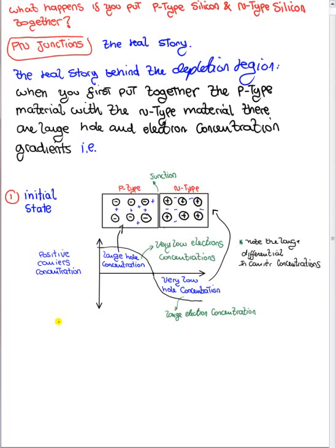Due to this large differential in carrier concentrations, opposite mobile carriers rapidly rush or diffuse toward each other, annihilating in a process that is called annihilation. They are annihilating each other, leaving a region depleted of mobile carriers, or a depletion region, which is what we hear people mention a lot. So let's write it down.